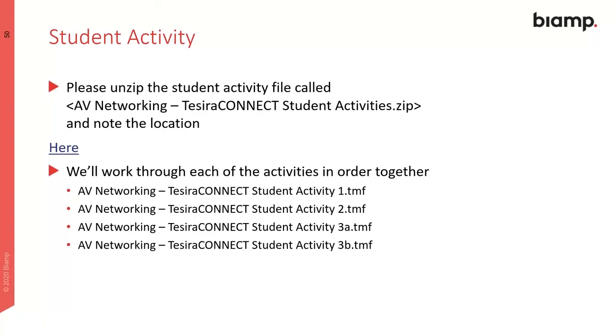You can, of course, go into the equipment table, add gear manually, or in the software fix certain blocks to certain types of devices. So that becomes a little more complicated. But there's no automatic way where you simply add equipment in the equipment table and it comes up with something. You still have to put in your DSP blocks and create a valid configuration.